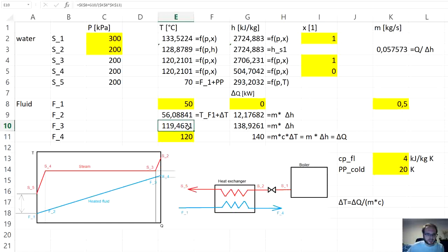And you can see it also here that here is almost 139 kilowatts of transferred heat, and the superheated steam transfers just 1 kilowatt of the whole 140 kilowatts transferred, so actually less than 1%. Which also shows that the superheated steam has quite low specific heat capacity.